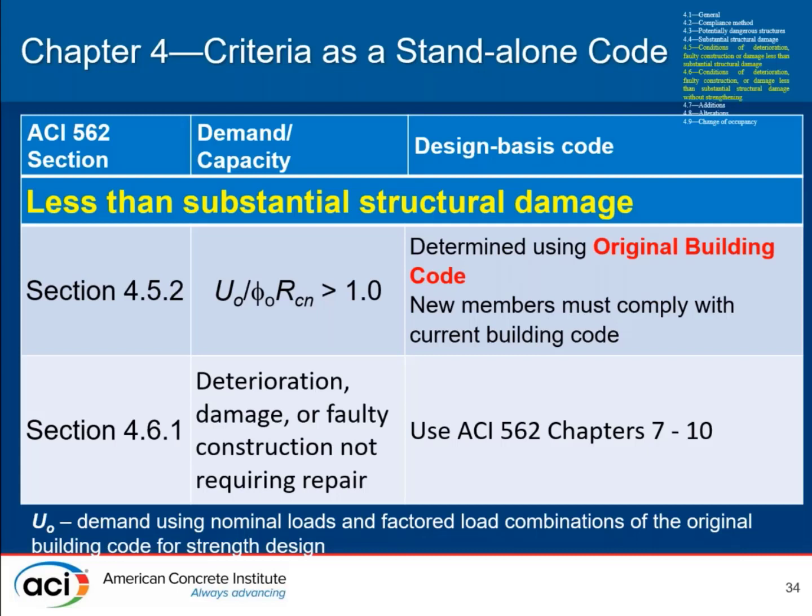There's also clause 4.6, where the LDP may determine, in a preliminary assessment based on engineering judgment and without analysis, that you can carry out repairs using the original building code if the historical performance of the structure and physical observation of the structural condition of the members and systems indicate acceptable behavior precluding evaluation by 4.3 or 4.4.